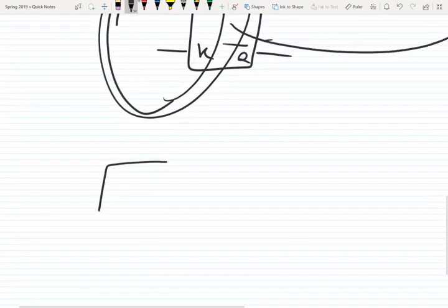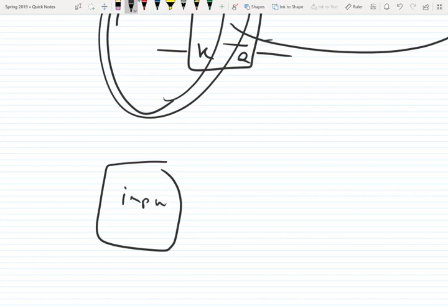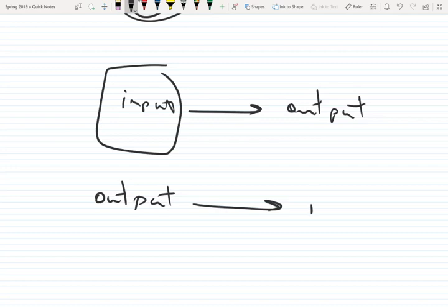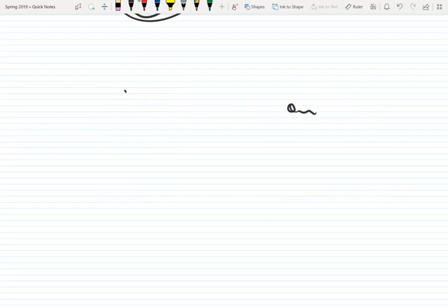So far we had inputs and we found outputs with the characteristic table, but in the excitation table we have outputs and we want to find inputs. That's very important. So how can we do that? We easily write the excitation table of flip-flops using the characteristic table. Let me show you.